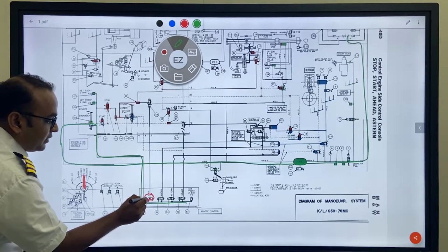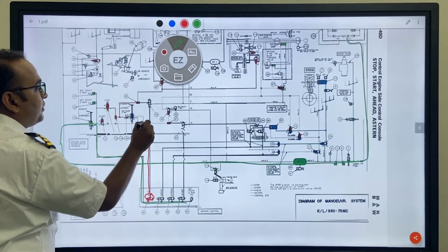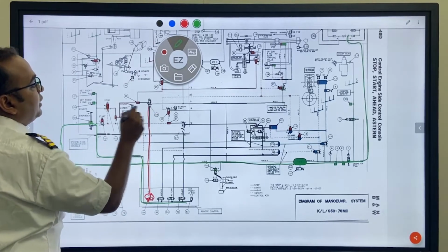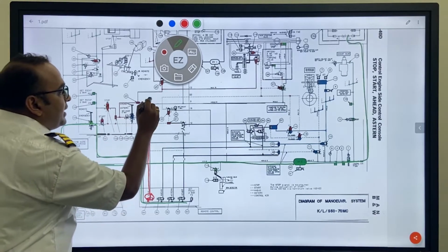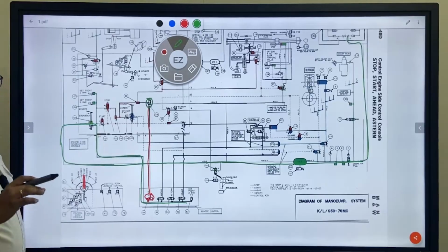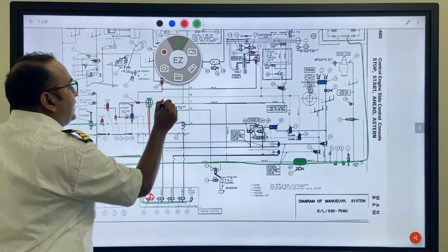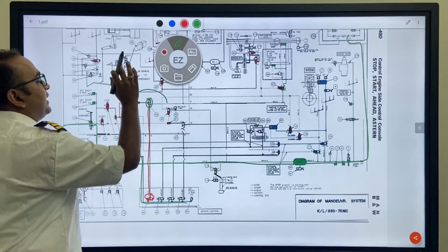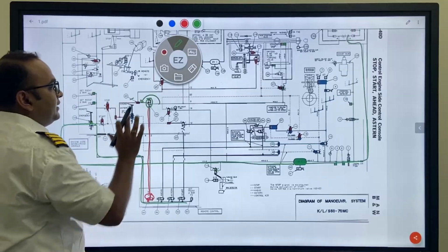As a result, air got a path to go up and activate valve number 38. This is valve number 38, and it gets activated. Once the valve is activated, this side air can cross to this side, right?